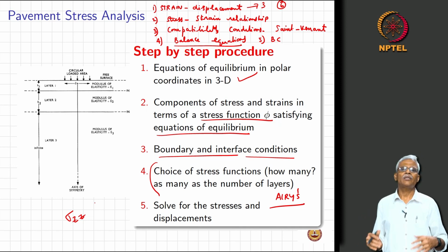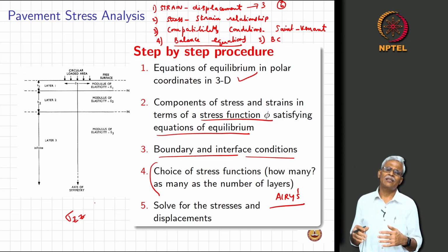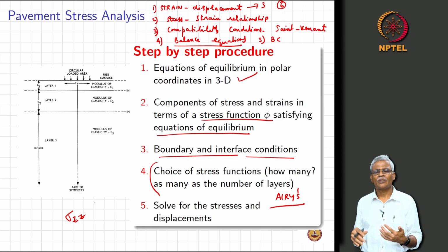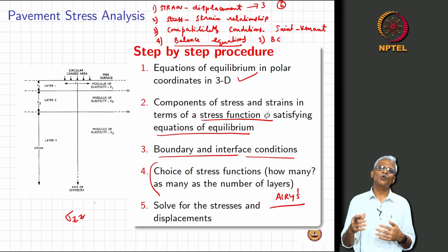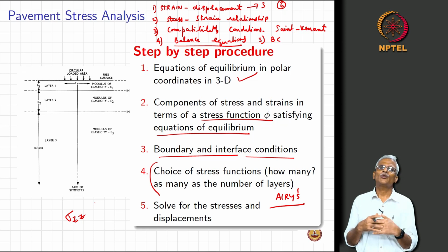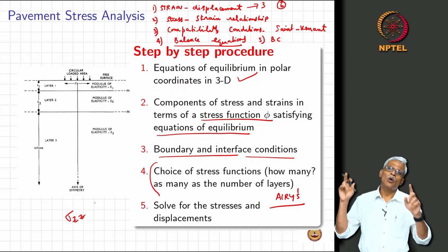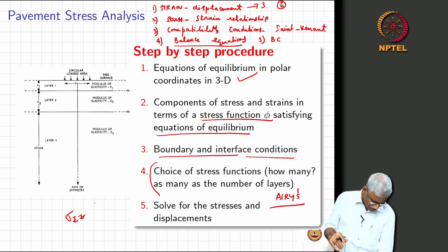For a moment, since our focus is more on pavement engineering, design and analysis, we will restrict our attention to that, and we will be using software like IIT Pave or KenPave to compute the stresses and strains. But you need to know that these are the steps followed here, because unless you assume something like a no slip condition, unless you assume that I am only going to apply vertical stresses and not worry about horizontal traction or shear stresses, you will not know how you got all these things. Okay. So, just keep that in mind.